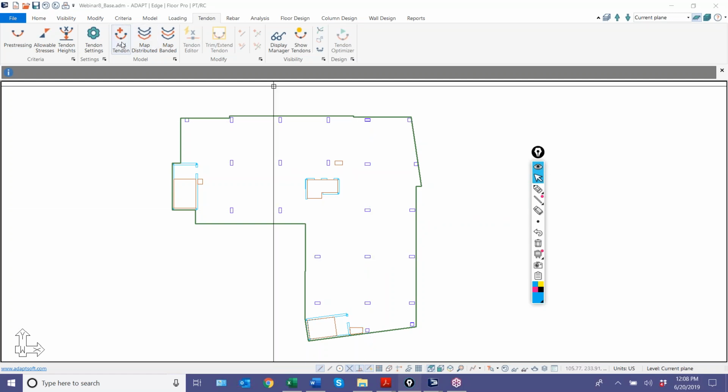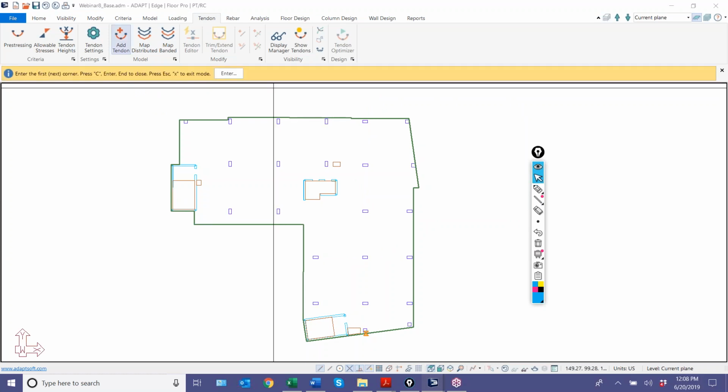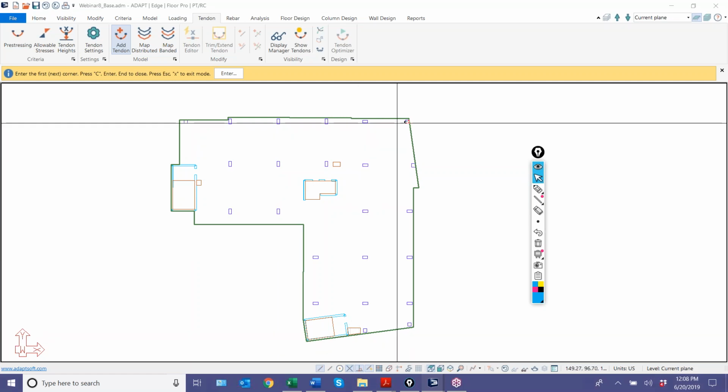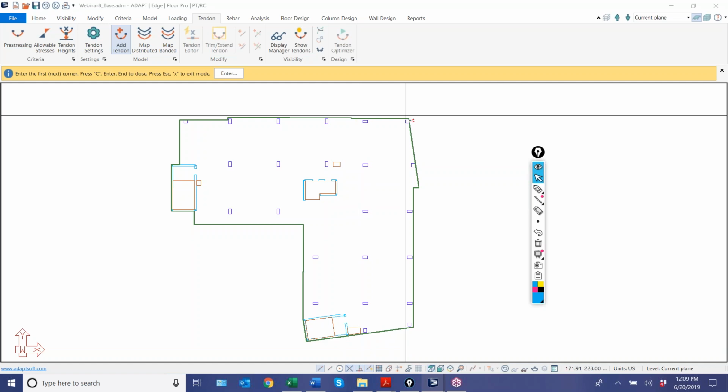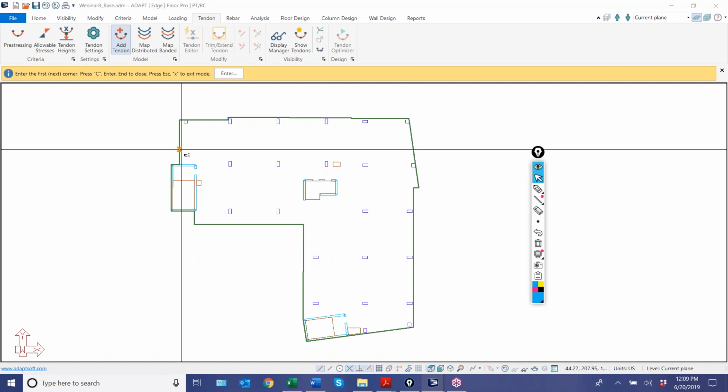So here we're going to add a tendon. This is manual modification, or manual input, of a cable. We're going to select a cable. I recommend when you're drawing cables, don't flip-flop the direction. You can flip-flop the live and dead end if you need to, if it's stressed from only one end. But if you model from bottom up and then top down, and you go into the tendon properties dialog window, the dialog window is always based on first point to last point. If your first point is at the top or at the right going to the left, you're likely to become confused. It takes a little time to get used to when everything is flip-flopped.